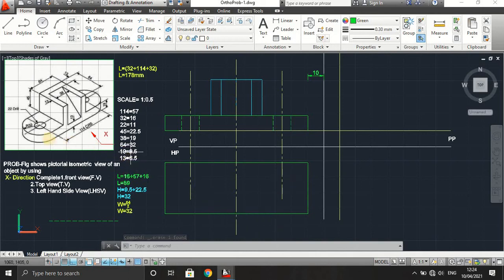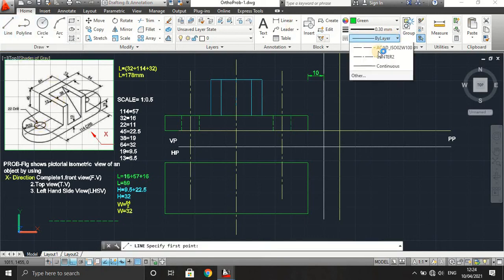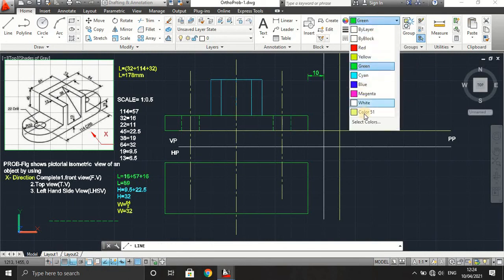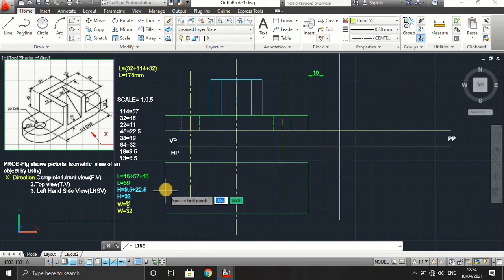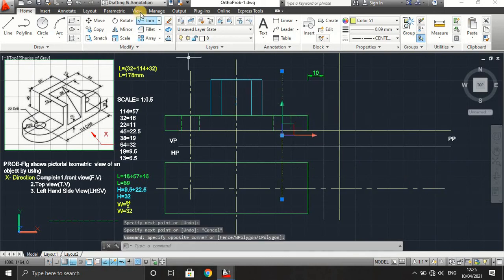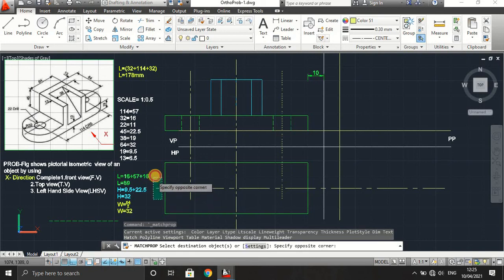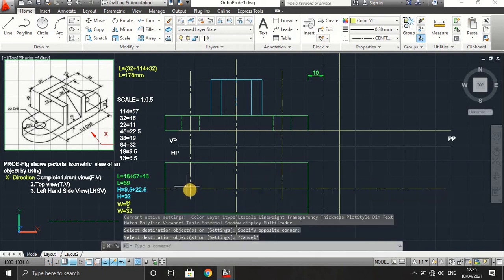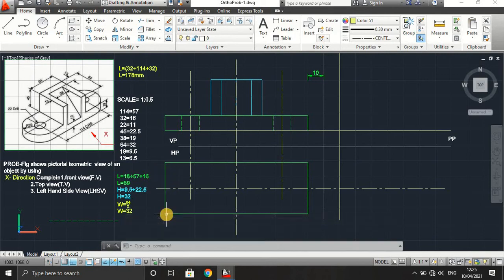Now at exactly the center we can find the hole centers. Select the midpoint, 16 mm, and at the exact hole position we get the center line. That is a total 32 mm, with half scale 16 mm, we can draw the center line and get the center points of the hole.